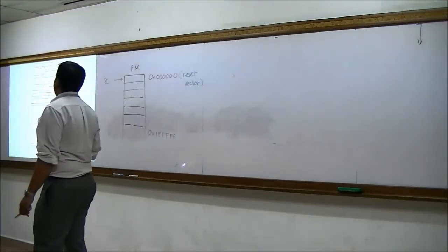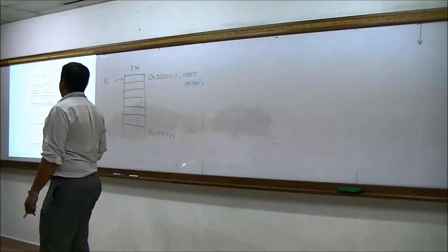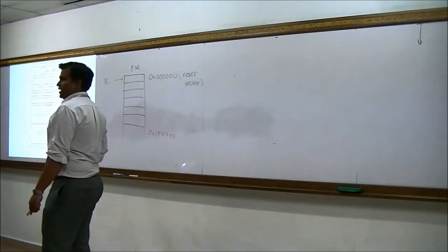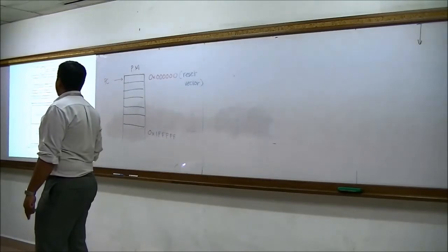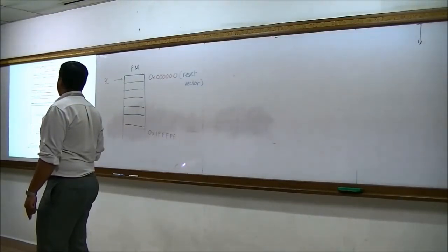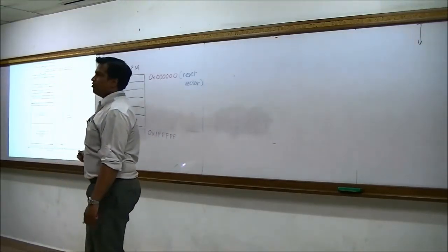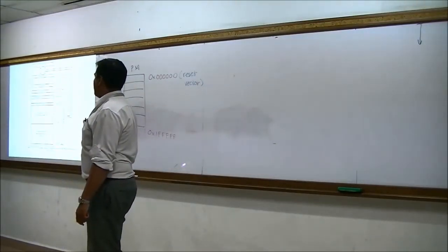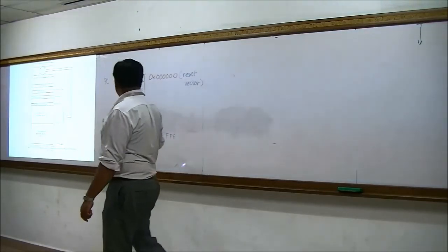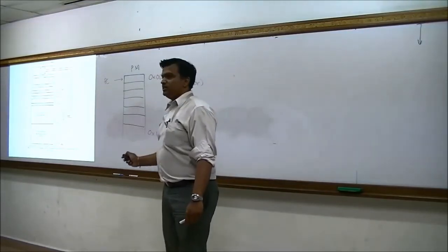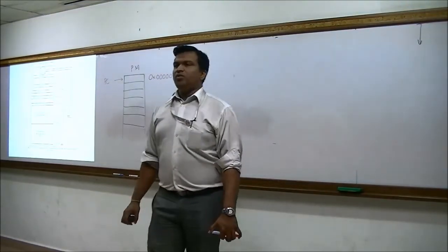So this is actually the diagram, which we'll cover later. This is your PC. Because it has 21 bits, it can access these 2 million locations. You see this first one is known as the reset vector. Of course you have the high priority interrupt and low priority interrupt. We'll revisit them in chapter 6, so for now you can forget about it. It goes up to a maximum of 1FFFFF as we have written here. This return address tag we will see in chapter 4, so for now I'm skipping that.